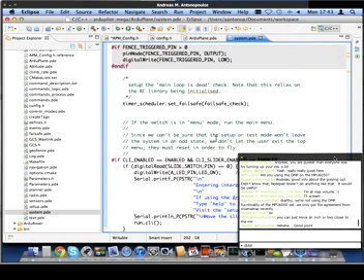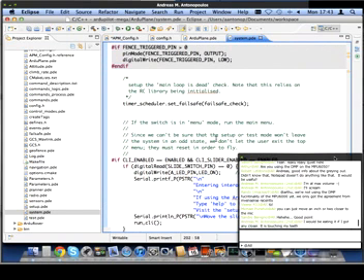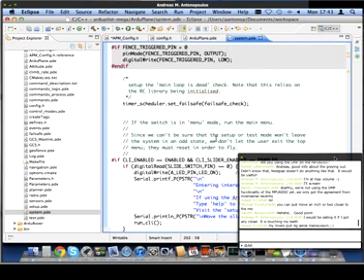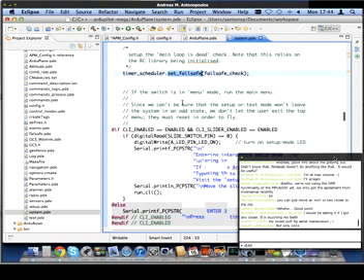The timer scheduler is perhaps one of the least well understood but most important aspects. The new current code in ArduPlane and ArduCopter use a 1 kilohertz timer for many things. So we use one of the built-in hardware timers to generate a 1 kilohertz interrupt, and that interrupt provides a heartbeat, or a regular calling of several functions inside the code. For example, it provides the heartbeat behind the APM2 barometer.